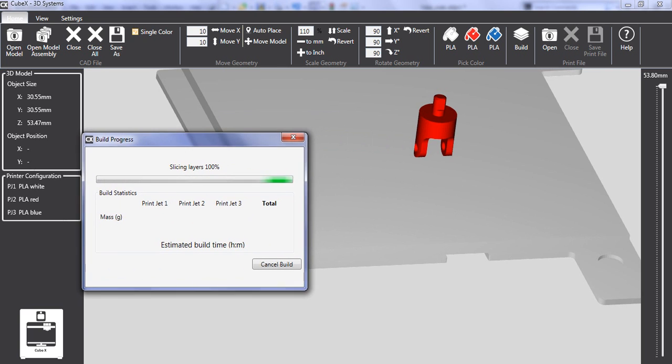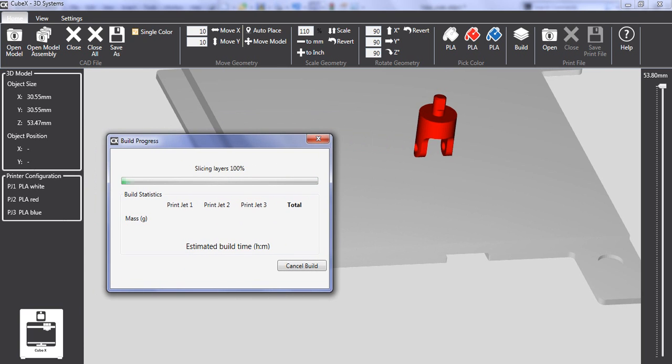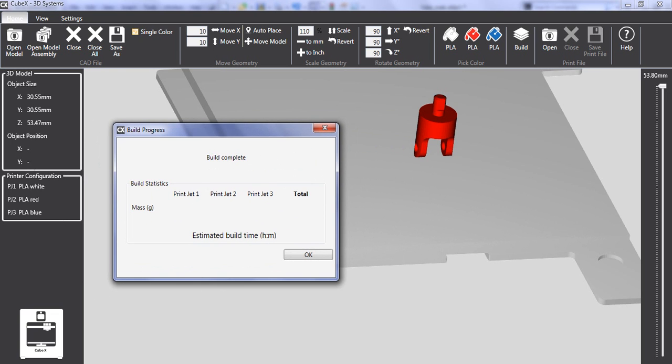Other than that, there are a few other things that are important when using this 3D printer. Number one is you have to make sure you have good adhesion between the part and your platform. That's why you have to use that glue. The way you position your part is very important, where you have your support.